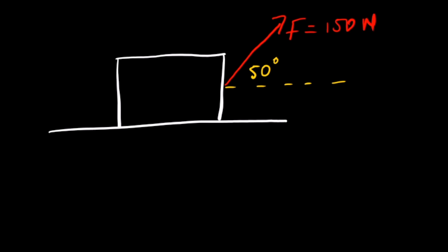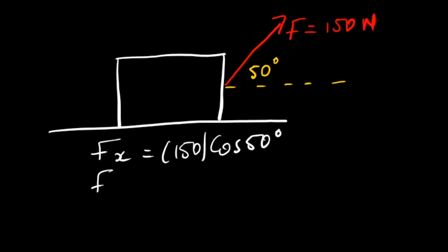Let us look at the next example. Pause the video, work out the answers, and play the video, verify your answers. We are resolving it into components. Calculate the components, Fx and Fy. Now for Fx, 150 cos 50, the answer should give you 96,42 newtons.